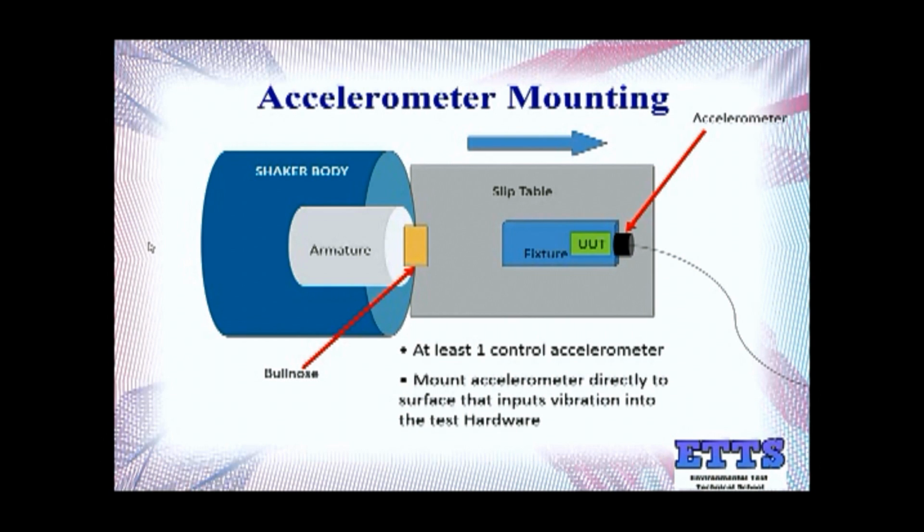That's just showing the direction of motion for your shaker system. And you can see this is a top mounted, or top connector, accelerometer. The cable connects to the top of the accelerometer, and you can see that it is mounted correctly in the axis of sensitivity.